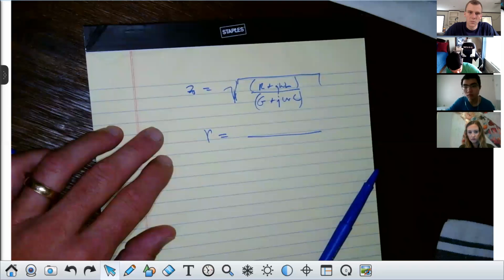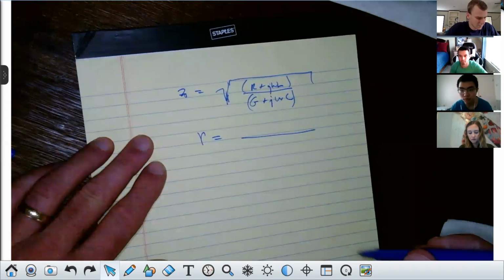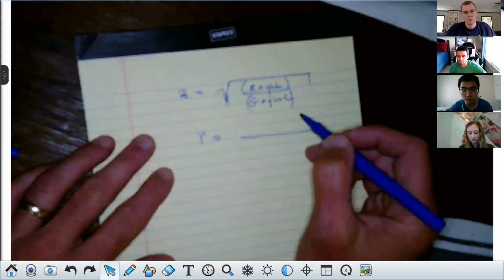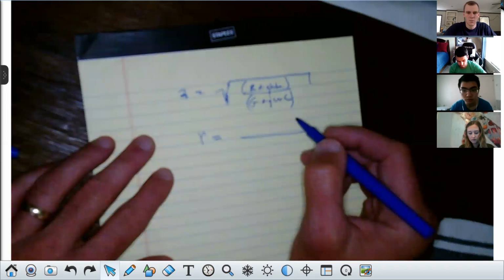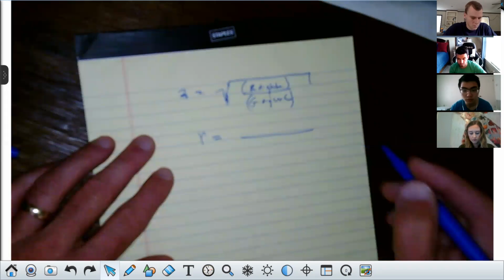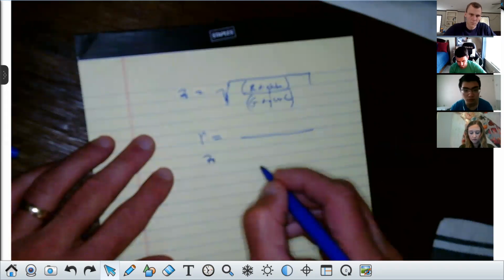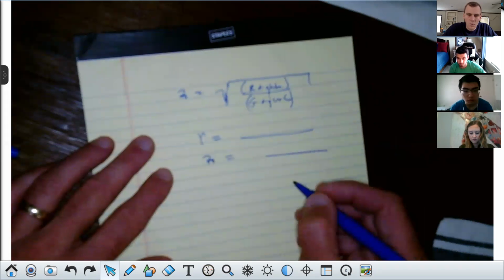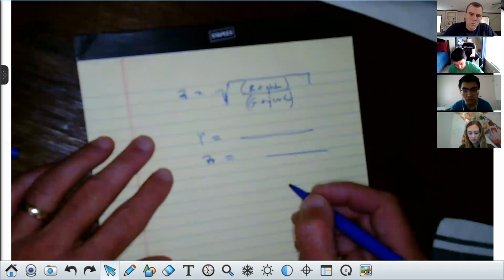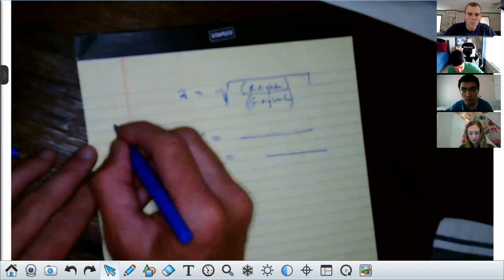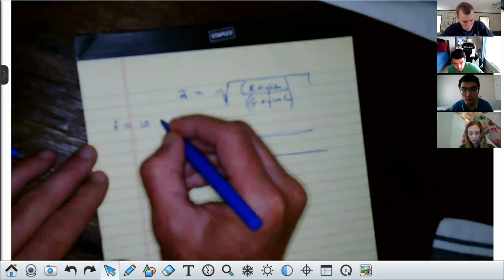All right, they give you Z naught and they give you gamma. I'll just leave gamma alone for now. It's 18.6 minus J.253, and they give you Z naught. They give you these two pieces of information, and they want the values of R, L, G, and C, and they give you a frequency of 100 megahertz, or 10 to the 8th hertz.